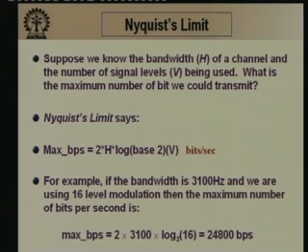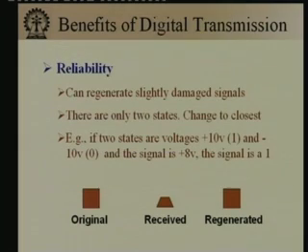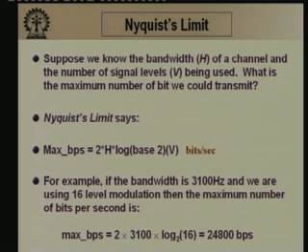And so far as the bandwidth of a channel is concerned, suppose we know the bandwidth H of a channel and the number of signal levels V being used, what is the maximum number of bits that we could transmit? Suppose we are trying to transmit bits in terms of a digital signal. There is a Nyquist limit which says maximum bits per second is 2 * H * log base 2